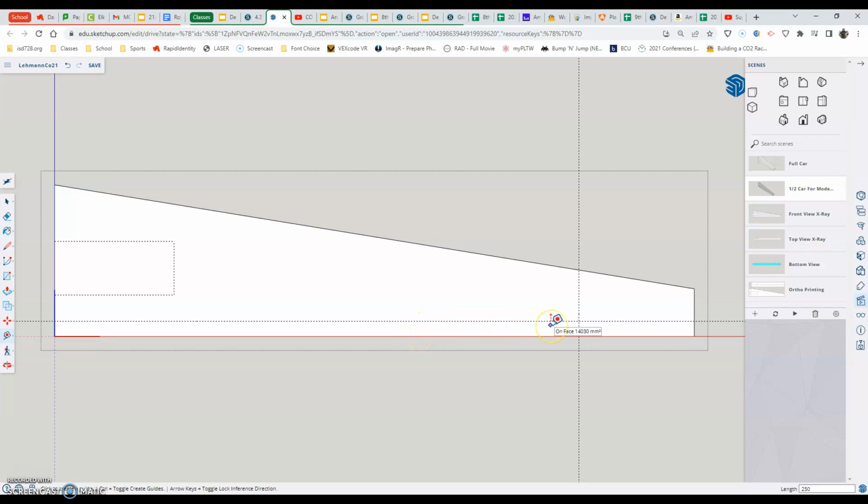But now I have a line coming up from the bottom edge that was already there. That's the height from the bottom edge where our axles will be. And then I also have one from the front to the back where that line is going to be, and that's the cut of our car as far as the length overall. Now, how we cut this is we want to go into our pencil tool right away here, and we want to connect what we just made on our intersection. Click down to the other side where you can find another intersection, and now we have a front straight line.